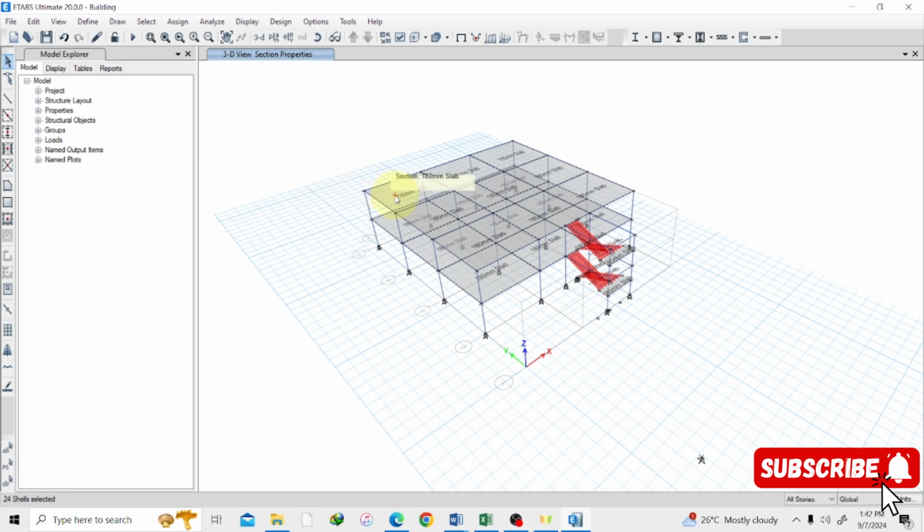Looking at this, our slab has already been meshed, but it's a default. ETABS has its own default mesh, but I don't really like to use the default mesh because when you are analyzing slabs of irregular shapes, it causes some form of inaccuracies. So you should make sure that you assign your own mesh to the slab.